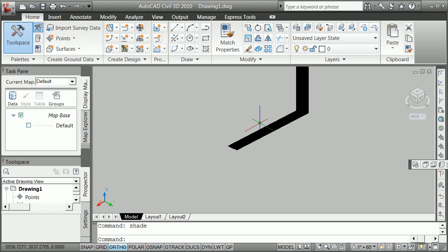You have to realize that when you are designing a road, what you need to do is keep track of your horizontal proposed, your vertical proposed, your assemblies, which is essentially your typical cross sections, and where they transition from one thing to the other. I've mentioned before that you can do a lot of this stuff just as fast. It's not as good, but this stuff's pretty good stuff we got right here.